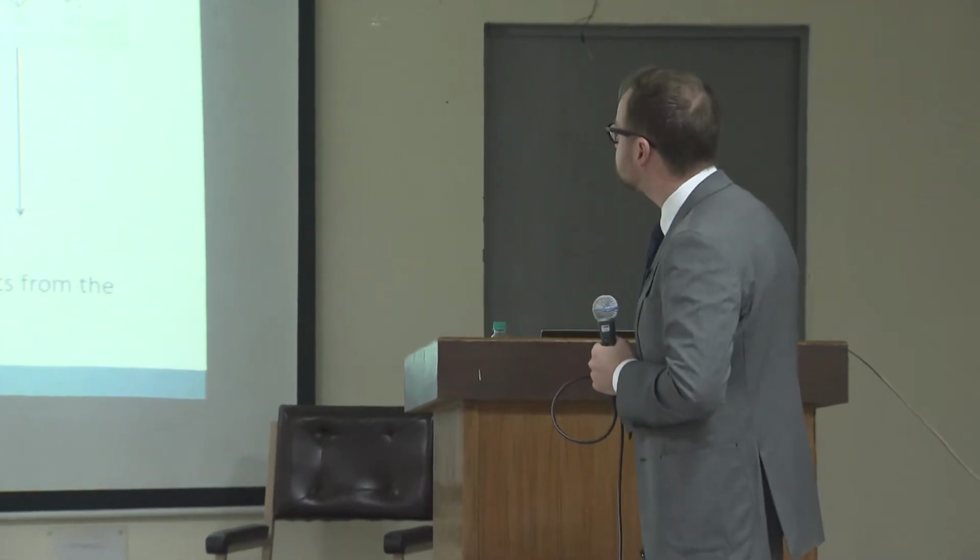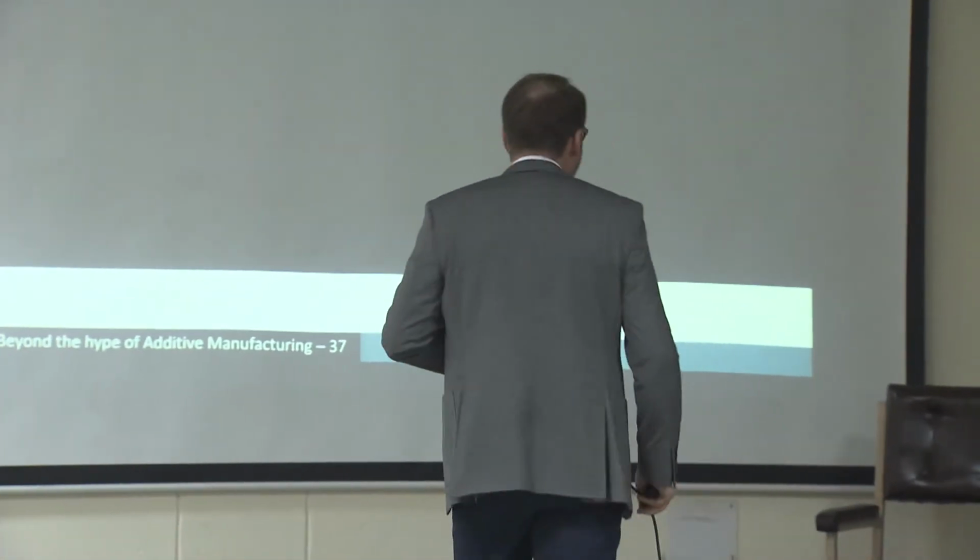So that was 4D printing. And then another upcoming topic is high-speed printing, both for polymers and for metals. Why is that important? Well, you already saw earlier the video of fused deposition modeling needed to be sped up because this takes time. Yeah? I've wasted far too many hours sitting in front of a 3D printer looking at it mesmerized. But the fact that I wasted hours and not minutes already tells you that all of this is slow. Yeah? Again, this is why mass production is not going to work well with AM. So there's a lot of work in speeding up additive manufacturing.